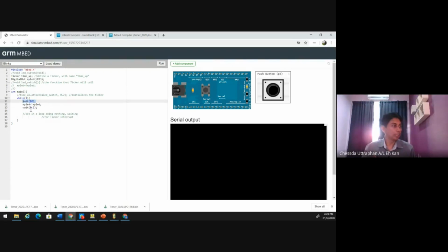When you do this, it goes to wait 10 seconds, and the microprocessor is processing the wait. So here, instead of flashing the LED every 0.2 second, now it flashes your LED every 10.2 seconds.